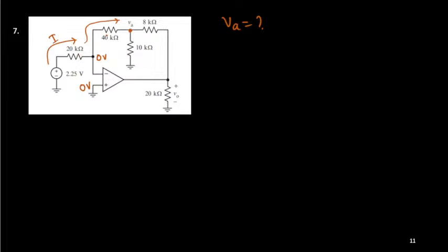Can you check this thing? Because this potential is Vi minus 0 by R1, and if I consider this is RF, then 0 minus Va upon RF, so you will be getting Va equals minus RF by R1 times these things. Am I clear? So you can see this thing.